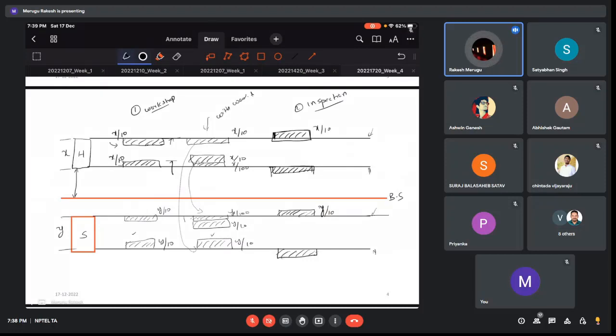So these tolerances are outside the actual tolerance. So I am also accepting some of the products which are not within the limits, as someone said earlier. So that was the difficulty with inspection gauges. There are some products which are not actually within the range of my selection, but still I'm accepting them. That's the problem with the inspection gauges.